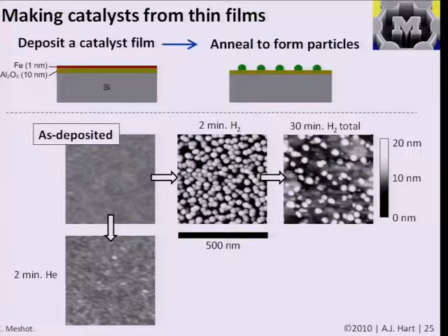But here we have a case where the basic technology of depositing a thin film, understanding how the thin film material wets the substrate, and then how the precursor would come in and grow the nanotubes from these nanoparticles, all those steps are important for then producing the final film of nanostructures that we want.